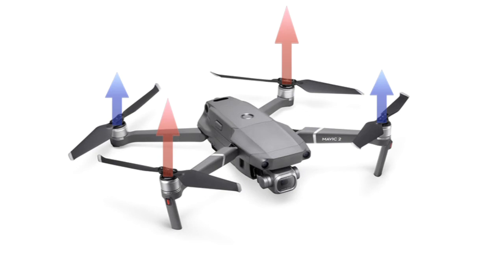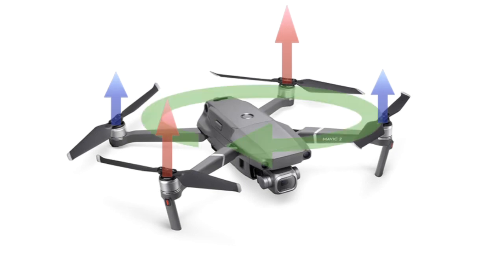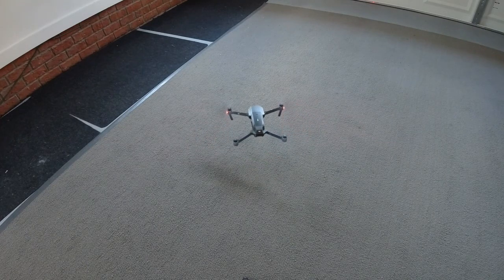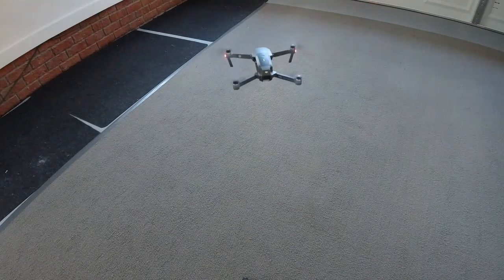However, the drone is now generating more counterclockwise angular momentum, so to conserve angular momentum, the drone will begin to yaw clockwise. Now for flying with a real drone. As you will see, hovering requires constant adjustments by the onboard flight system.